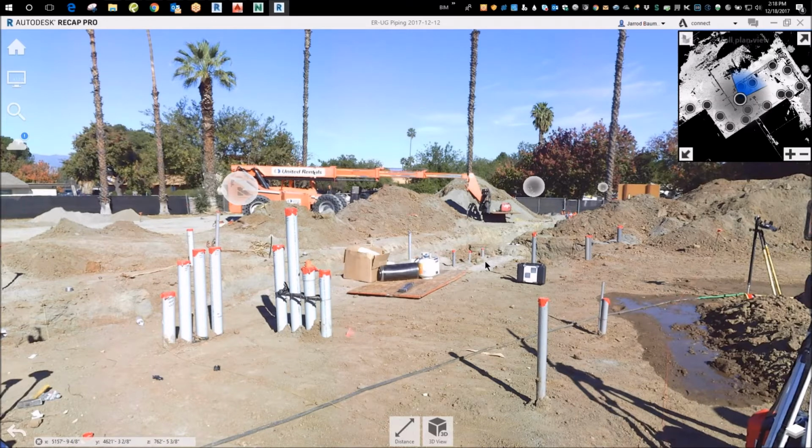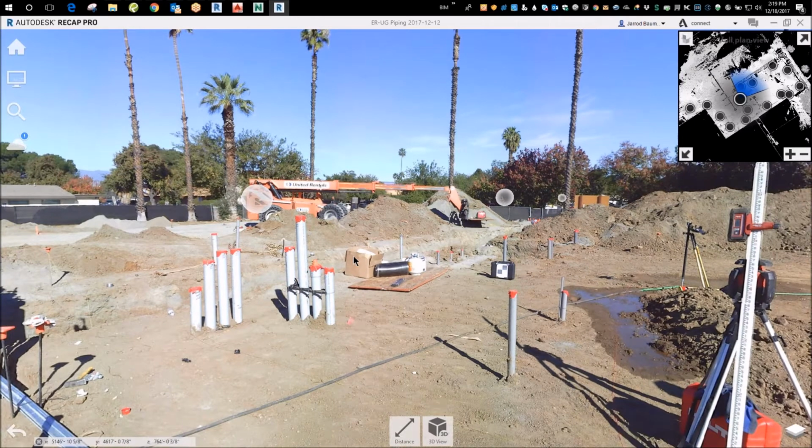So surveyors shoot typically in state plane coordinates. When they come into a site like this, where they're not necessarily trying to locate a new building on a new piece of property, they're trying to locate it in a local coordinate system and get it aligned to the existing building. They'll set up sometimes a local coordinate system like this, where the numbers are smaller, simpler, but they can do it either way. But most of our other projects, though, Etiwanda, Mount Sac, those are all state plane. We're working in 1 million or closer to 2 million, 6 million coordinate systems.